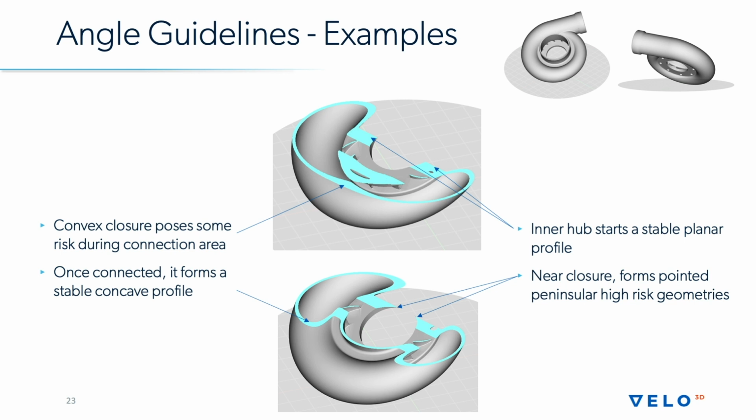And when you're thinking about just this geometry, you can think about the tilted tube rule then, right? It's starting to form this nice stable concave shape. And remember, the rule there is 100 millimeters thereabouts at 10 degrees or higher tilted angle. And so the lowest angle is right here, and it actually nestles itself, although it's not a complete closed tube, the lowest angle feature here of this curve is well within a nice stable concave shape. And so it behaves similarly to an inward growing cone locally. You could think about that here.